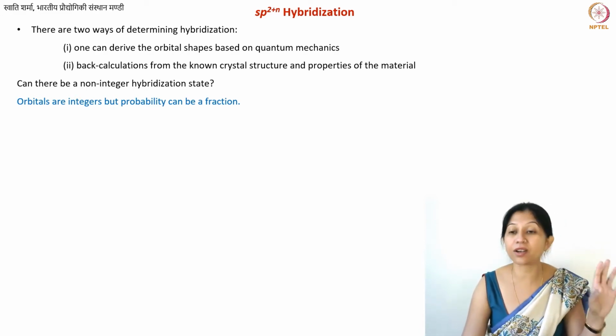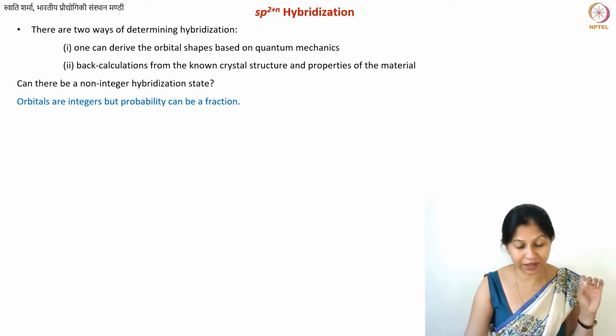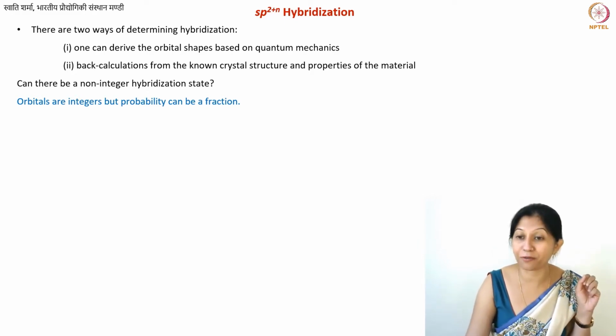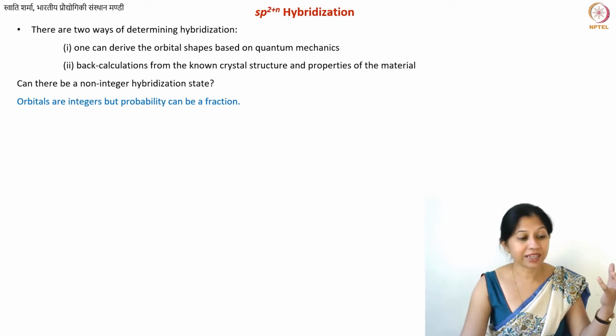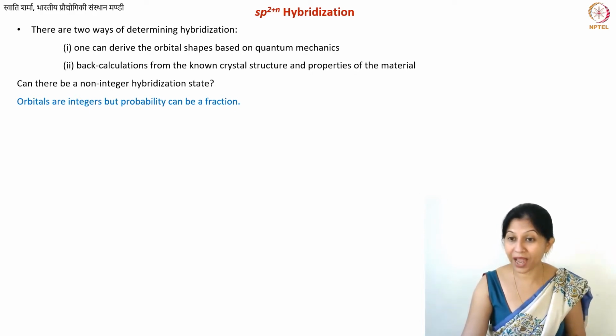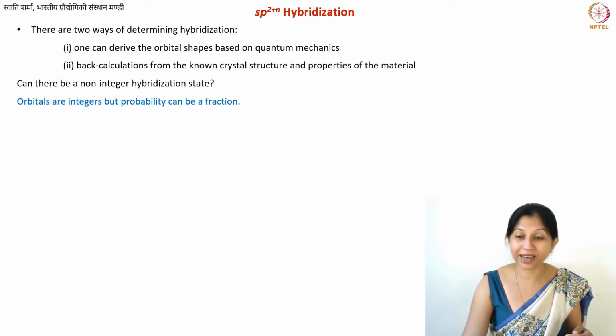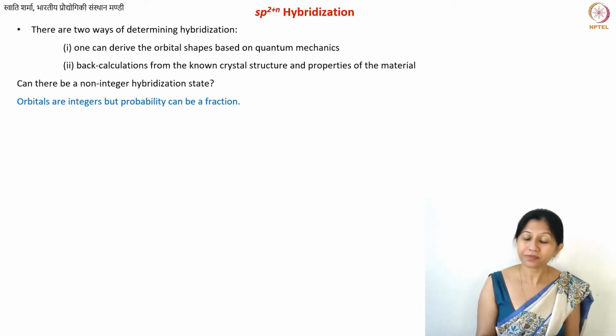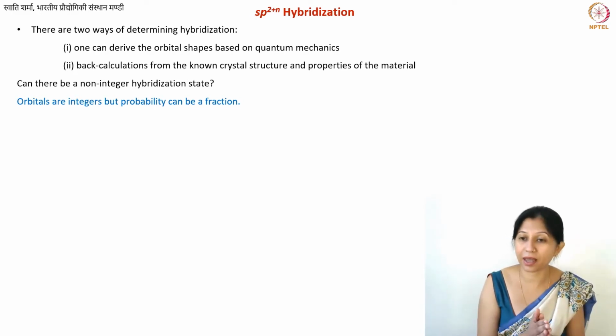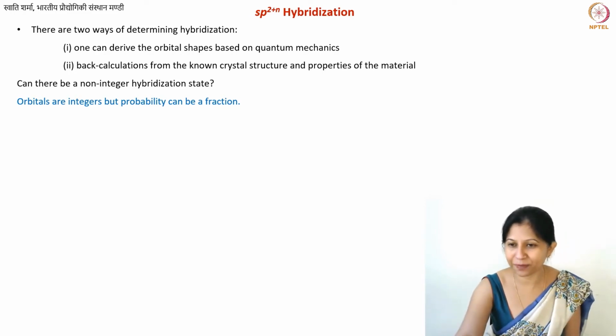So even if you did not know the material at crystalline level, even if you did not know what type of hybridization it possesses, even in that case, just by observing the behavior of the material at the time of manufacturing, you can understand the type of hybridization it can have. So for us it is, as I said, easier to back calculate. We are also going to often encounter carbon materials which are curved, Buckminster Fullerenes being the most common example. So we can also now back calculate the hybridization from there. Let's try to do it in this particular lecture.